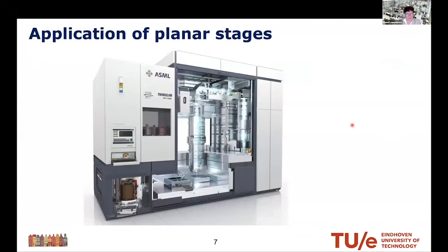Let's take a look a little bit more at this device to see the heart of that machine. So we have a very intensive arrangement of lenses or mirrors for focusing the images from the reticle stage, which is identical to the wafer stage, and to produce the images on the wafer. A fast change of the reticles on top of the machine allows us to intensively change the production of the images on the wafers. Besides that, it's not only production of the images on the semiconductor platform, but also inspection of the wafers after several steps of illumination of the images.